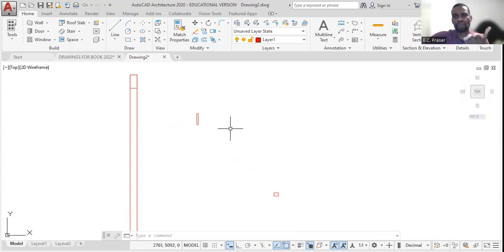Now my soffit. In this case, I want a closed fill eave detail. So my soffit is typically an overhang of 450, and the board is probably a half inch thick board, so I should make this 13.